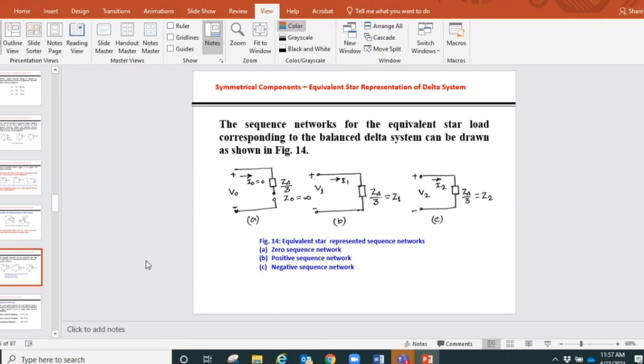First of all, whatever frequency we choose, it has this relationship, F equals Pn over 120, that you have learned from the fundamentals. P is the number of poles of the generators and motors, and N is the rotational speed in revolutions per minute, and that gives the frequency.